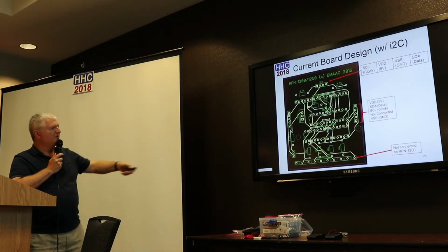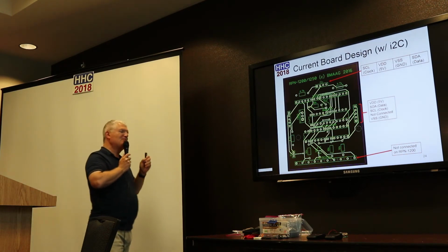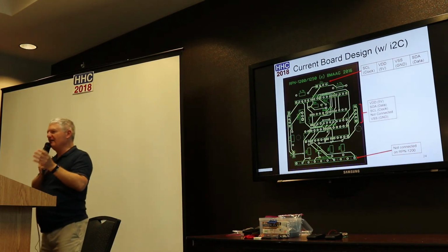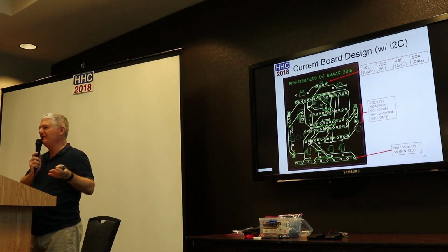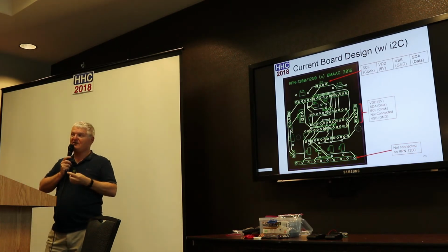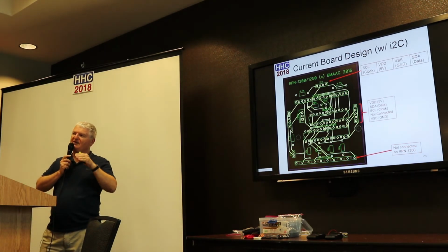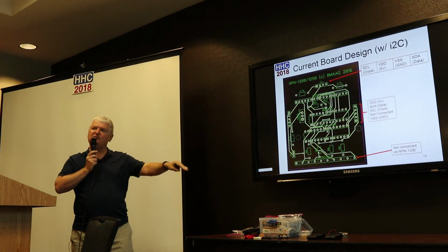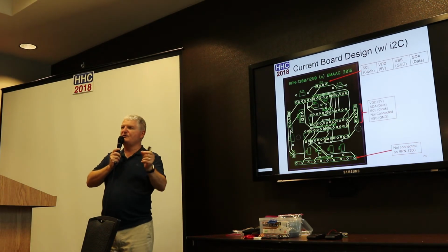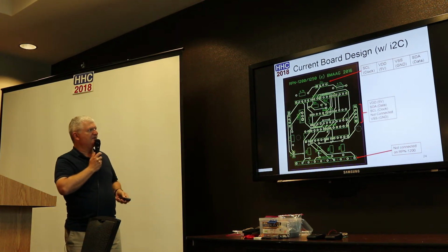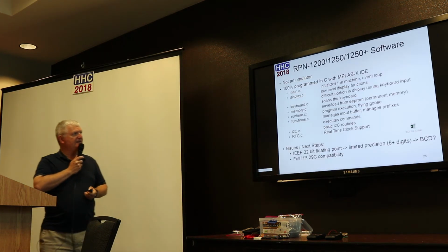So that's what the board looks like. One of the key problems I had is actually here, it's a connector. I designed everything with one connector, and then when I wanted to reorder it, it was not available anymore. So I had to find something that matches, and it's trial and error because it's not that easy in a catalog to find out exactly whether a switch is going to work for your project or not. And because we're fitting it into an existing casing, it has to match. But in the end, I think it's worked. So that's what the PCB looks like.